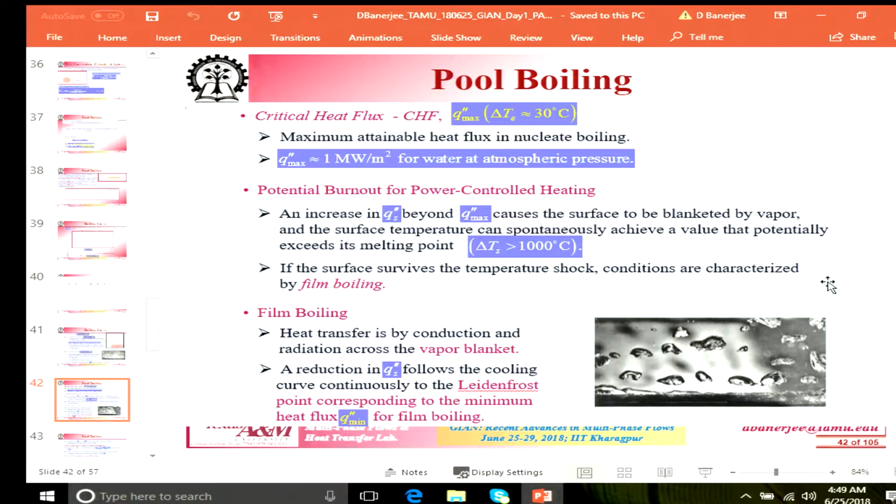The distance between two vapor bubbles, you can predict based on instability theory. There is something known as Taylor instability wavelength, which we are going to talk about tomorrow. What people find is that the periodicity between these vapor bubbles that are departing alternately from one location and the other, you can predict fairly well if you know the Taylor instability wavelength.